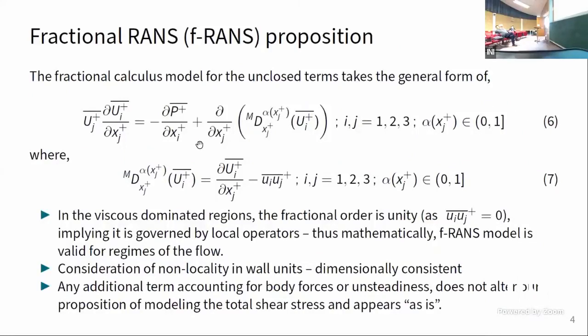Oh, okay. So just wanted to say to the colleagues from the other community that these equations are equations for U bar, which is what you need, but what you don't have is the UI UJ bar, the little ones. And so the whole problem is how are you going to approximate that little UI UJ, so as to have an equation that's only in the bar quantities. That is the problem. That's the fluid problem for fluid mechanics. I just wanted to explain that to those colleagues.